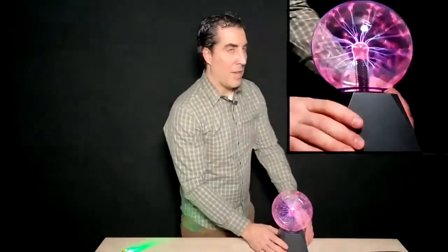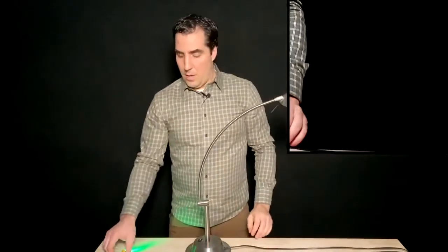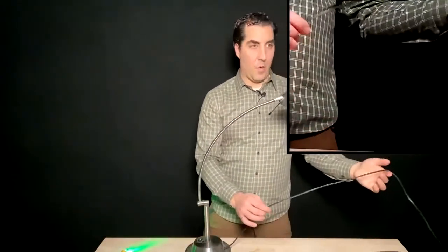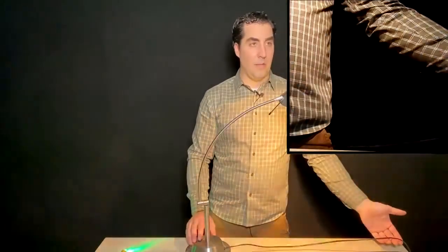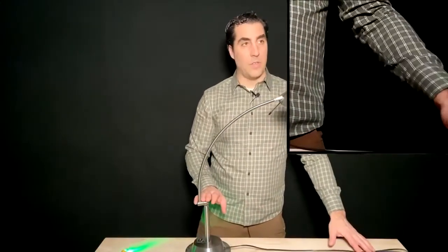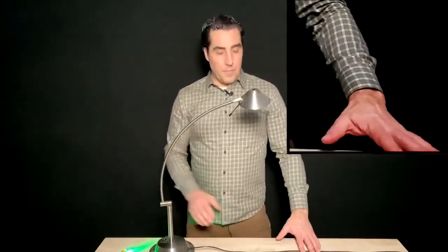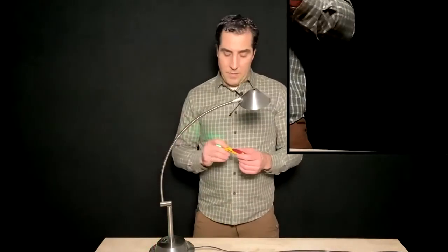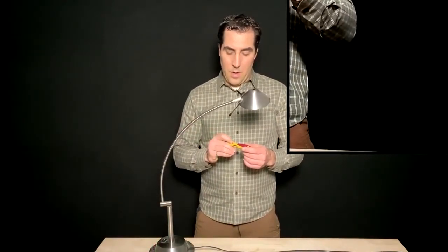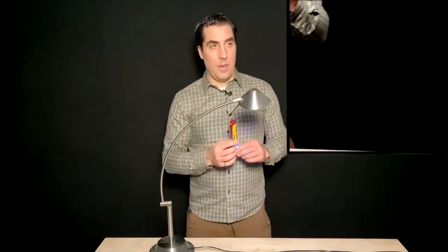So what happens when we look at a lamp, right? A lamp, for example, has a cord, and this is plugged in. So there's an electrical pressure or voltage induced on the cord up to the on-off switch of the lamp. I'll just move it around there, right? Now, I'm just going to change the setting on my voltage tester to be a little more sensitive. So now it's on a blue setting here.